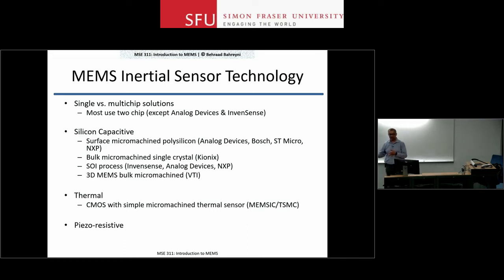If you go back historically, it started with piezo-resistive devices. Back in the early days of MEMS technology development, it was easier to make piezo resistors than capacitive devices because of the limitations of fabrication technologies. Basically, we didn't have DRIE back in the early 80s maybe. And for that reason, we had some piezo-resistive devices. Some of them are still produced because of compatibility that you want to have in a line of product. But as I said, the vast majority of the devices are now capacitive.